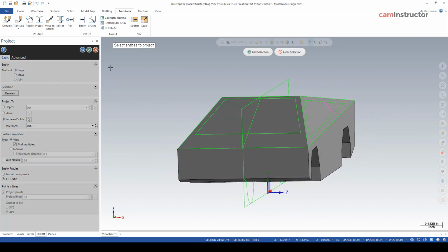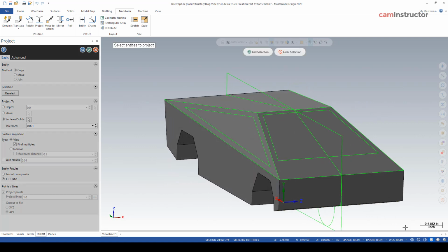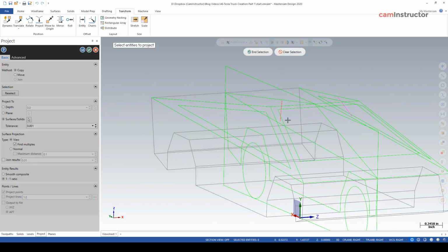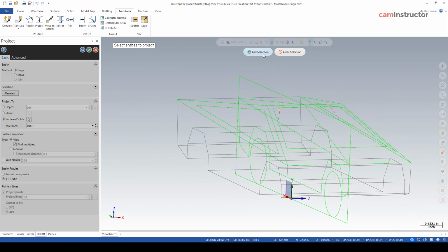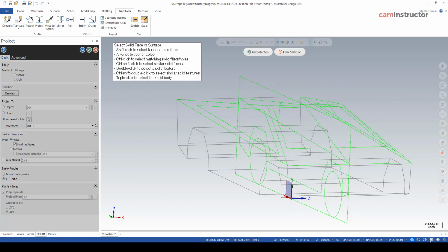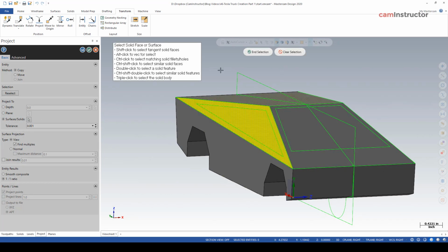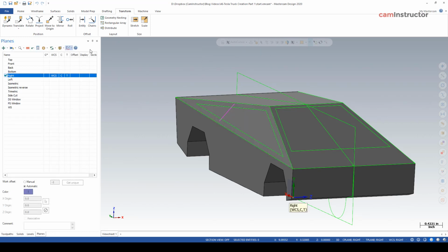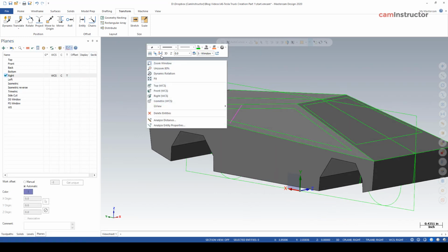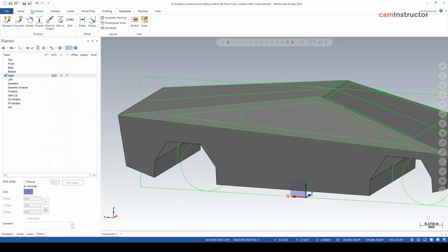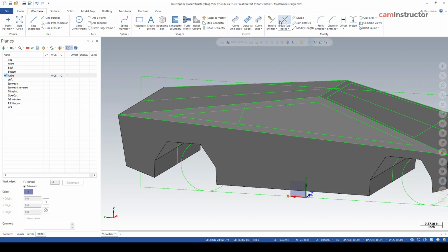Blue check mark to accept, because I'm going to do another projection. What do you want to project? Wireframe, that guy in the middle we drew, and selection. Where do you want to project to? Surfaces, select the surface, back to shading for solids, select this face, green check, and we're good. Let's do a clear colors again. So now we can go in and do some more trimming.